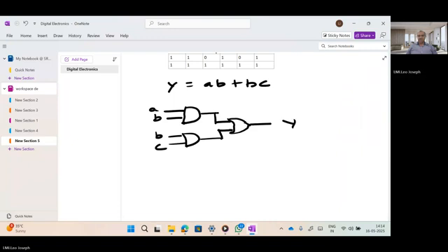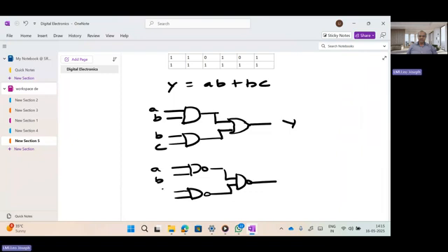This is Y. So if I want to realize this, yesterday in the lecture itself we explained how to convert an AND gate into a NAND gate and how to convert this OR gate into a NAND gate. Yesterday itself we explained. So directly I am drawing the circuit. So AND becomes NAND. This AND also will become NAND. And following this, another NAND gate will come. So this is the realization circuit. Whatever output we are expecting here, these two will be the same.